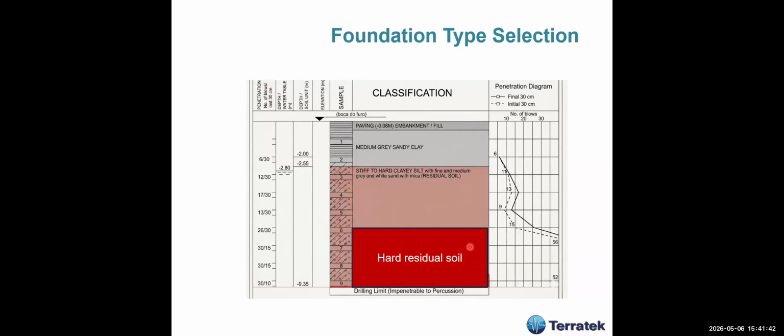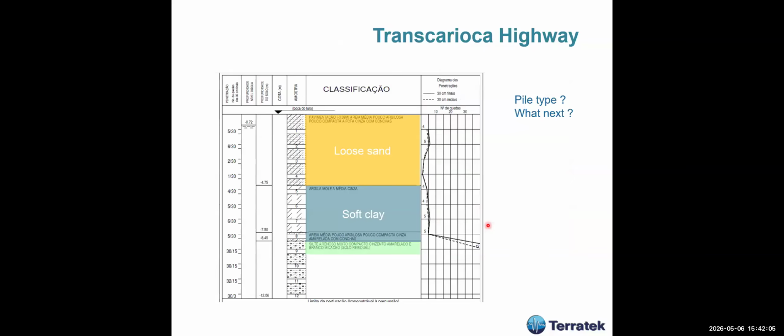So here, driven piles are out of the question, CFA piles are out of the question, micropiles, yes, micropiles could be used in this borehole because we can install the micropiles by drilling in this hard residual soil. Let's go ahead a little bit.